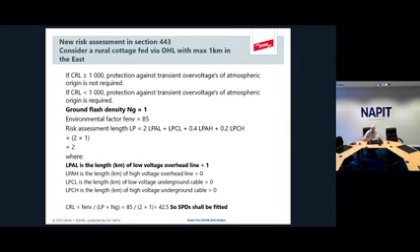I can see nothing but trees out there. So that gives me a hint I'm in the countryside. So my environmental factor is 85. If I was in the middle of town, it would be 850. The ground flash density for this area, I already know, is about 1. That's on the eastern side of the country. So this is a hot spot round here.